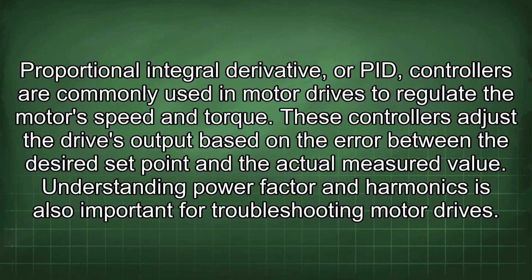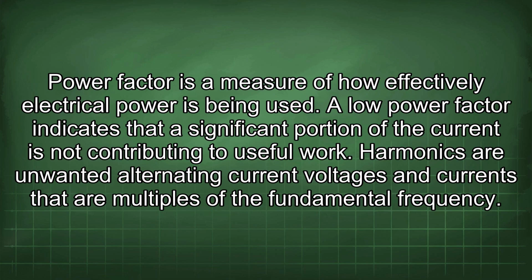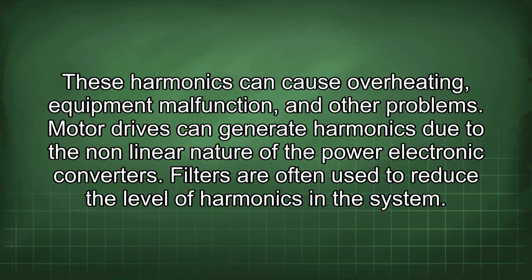Understanding power factor and harmonics is also important for troubleshooting motor drives. Power factor is a measure of how effectively electrical power is being used. A low power factor indicates that a significant portion of the current is not contributing to useful work. Harmonics are unwanted alternating current voltages and currents that are multiples of the fundamental frequency. These harmonics can cause overheating, equipment malfunction, and other problems. Motor drives can generate harmonics due to the nonlinear nature of the power electronic converters. Filters are often used to reduce the level of harmonics in the system.